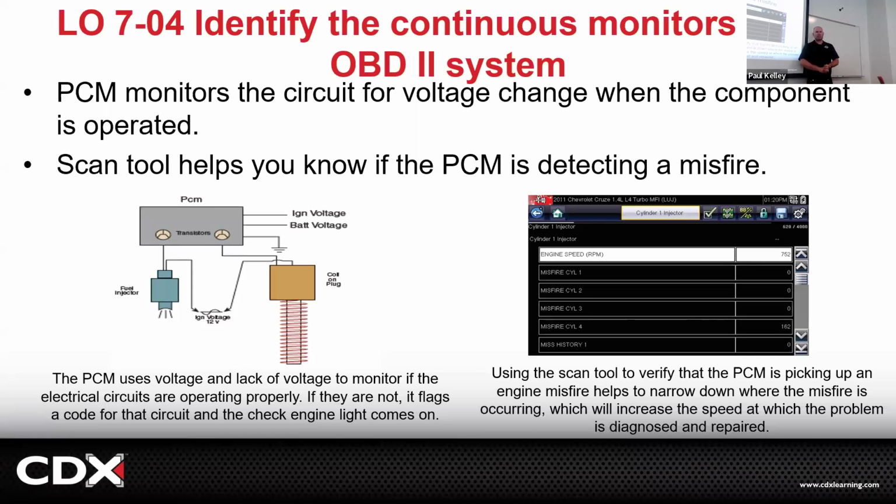No, so it doesn't set a crankshaft position sensor code. It sets a cylinder 3 misfire code because it's pretty sure that cylinder 3 is not firing, because it keeps slowing down pretty consistently when cylinder 3 should be speeding it up. Make sense? So that's a different type of code. The OBD system still set the code. It's just not necessarily monitoring voltage like this one. It's more advanced. It's actually monitoring the crankshaft speed through the crankshaft position sensor.